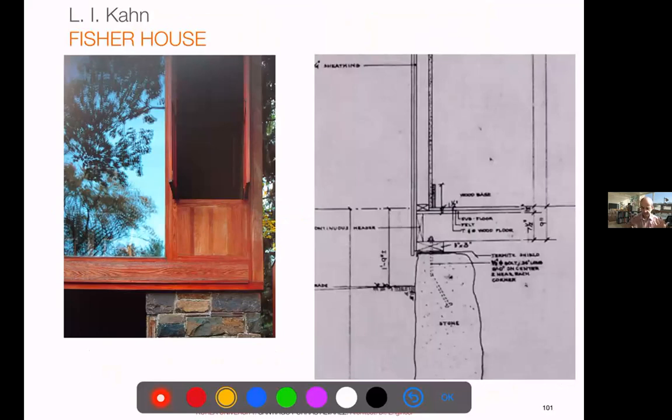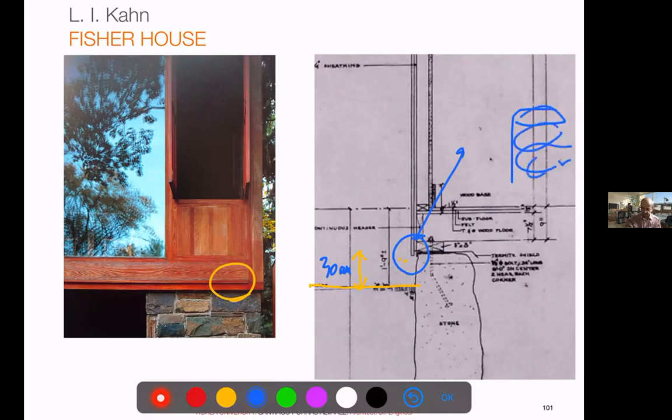Many things that we have to pay attention to. First is the separation of the ground from the sensitive material, which is timber, right? And usually it's about, sorry, about 30 centimeters or more, right? Then we have this small little bit. You see that if we enlarge this detail, we have the rubble stone material, right? And we have the timber,